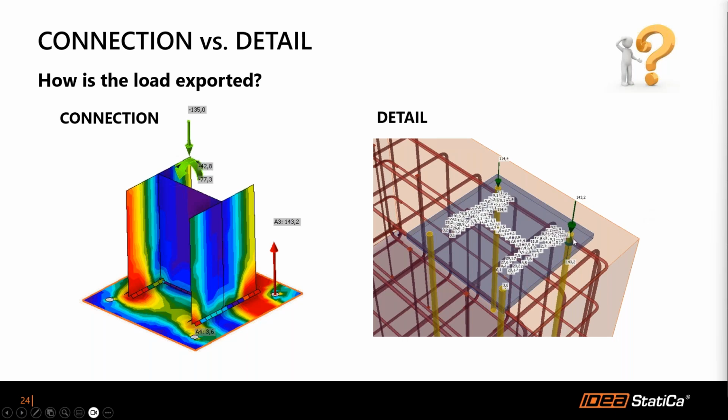First, there's a tension force in the anchor, and there's another one acting in the opposite direction, ultimately maintaining the equilibrium. This way, we are able to achieve consistency in the design. You can see that the bolt force over here in the anchor is matching perfectly.